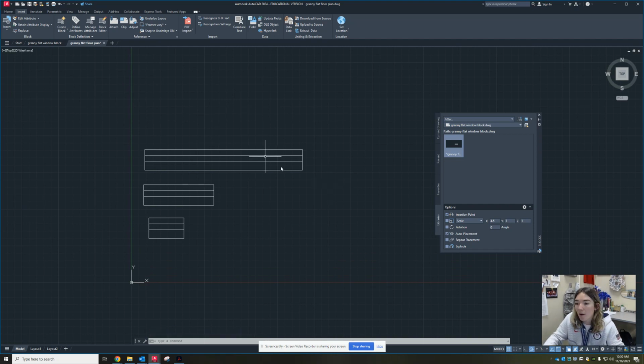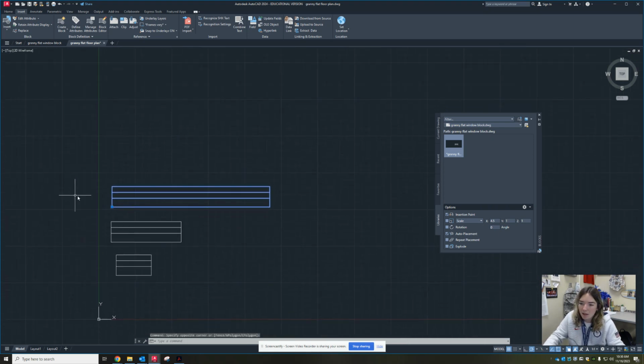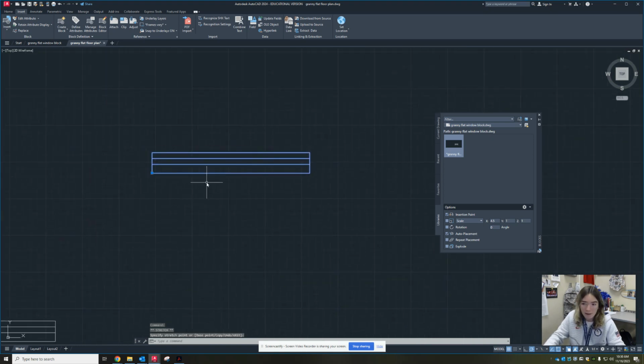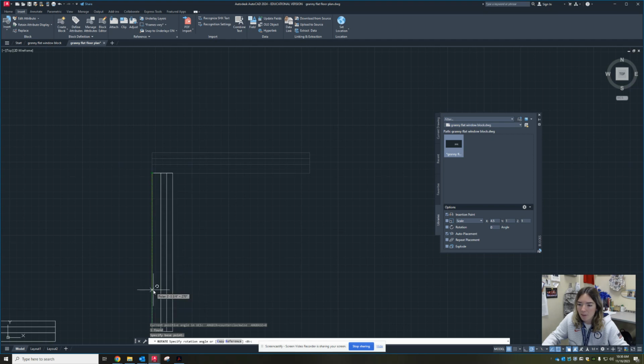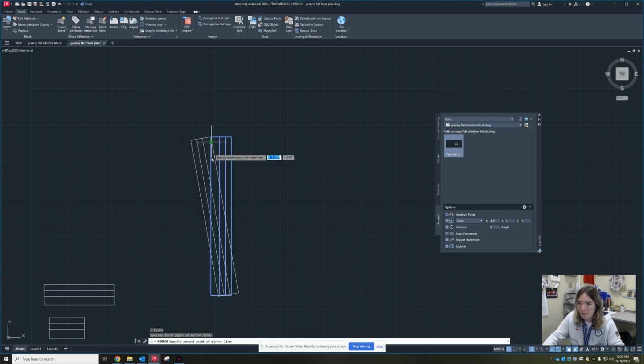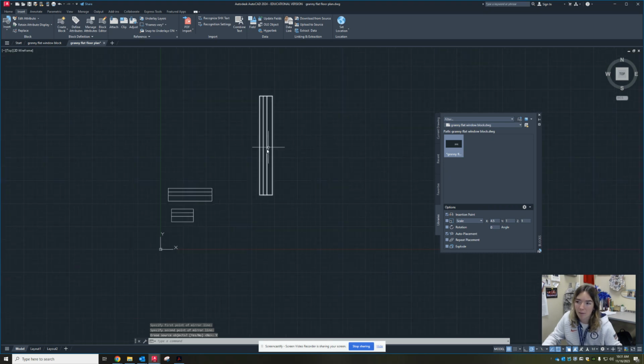And then from there, if I would like to rotate it, I can select my window. I can move it with this vertex, right, like this, to where I want it to go in my drawing. I can type in RO for rotate. This will allow me to rotate my drawing. Or I can select it and type in mirror, right? And this will allow me to mirror my drawing, like so. And I can delete, it says erase source objects. I can delete that first window I drew and I can keep it as just dimensioned, or I can leave it and have both. So that is 2 commands you can use to rotate these windows.